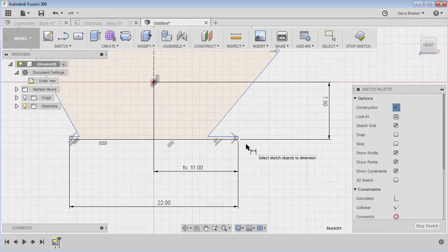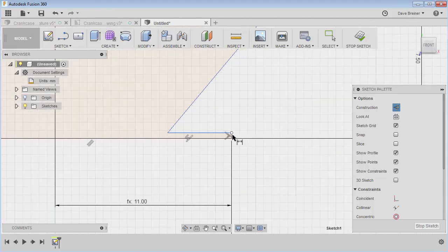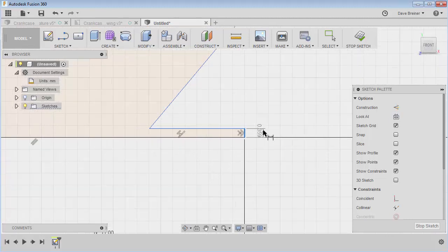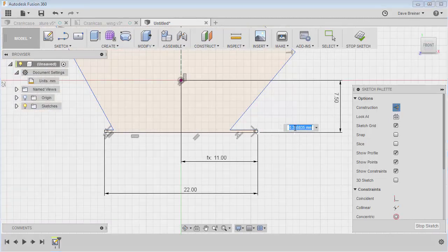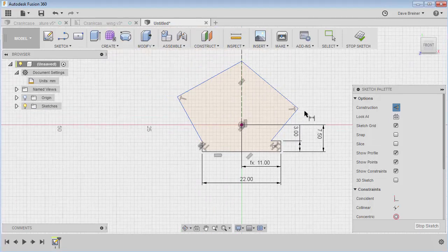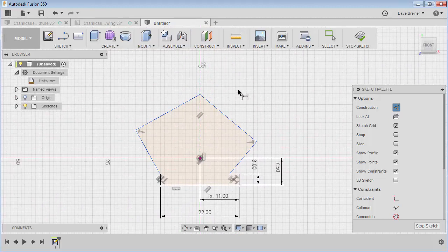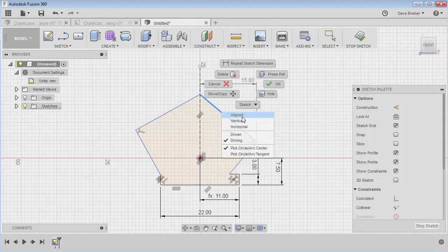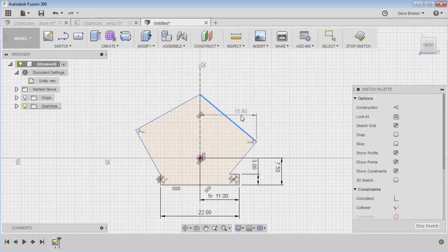And you can see right away that I better hurry up and get this one here. Let's get this there. And I'm going to pull this out, and this is going to be 3 millimeters. Much better. Okay, so I think right now I am going to apply this dimension, and you're going to see that I pulled out, it's got height, but if I leave it close, it'll stay aligned. If I happen to come up, I can right click and enforce a line dimension. So that's exactly what I want, and this is going to be 12.7.